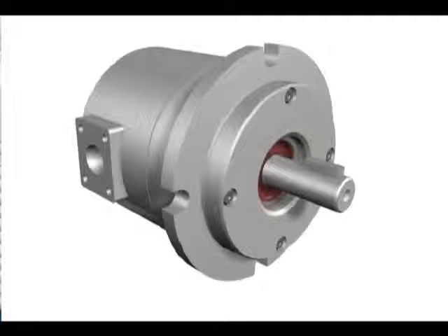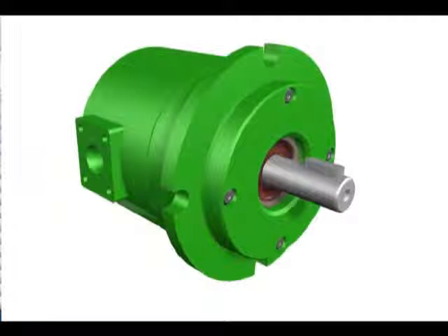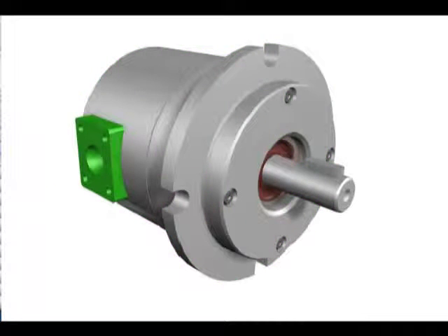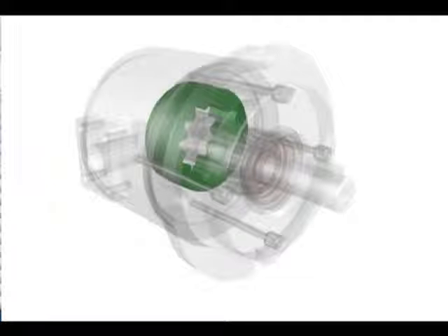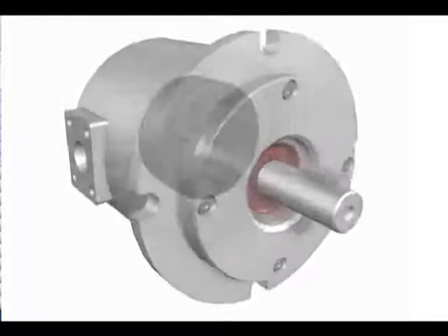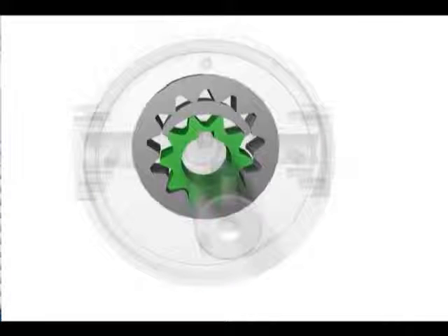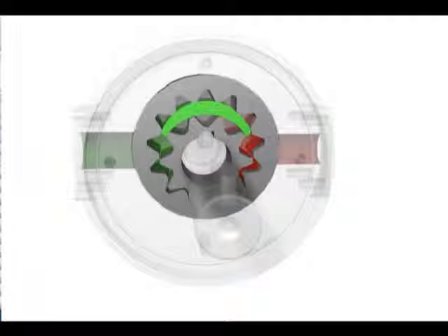The main components of the crescent pump design include the housing with a crescent seal and ports, the end cover, the input shaft, the drive gear, which is an external gear, and the ring gear, which is an internal gear. The drive gear, which has fewer teeth than the ring gear, sits offset in the ring gear. This creates an open cavity between the two gears. The crescent seal, which is machined into the housing, divides this cavity, creating a positive seal between the inlet and the outlet side of the pump.